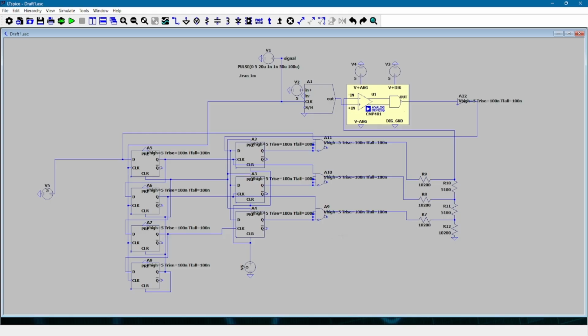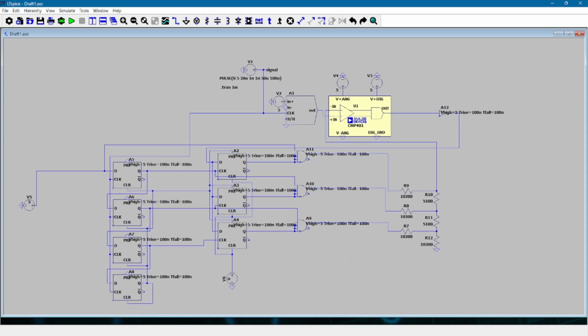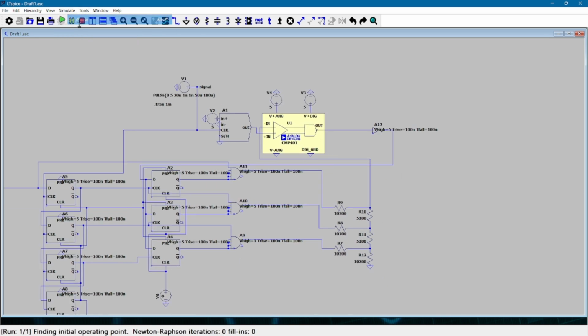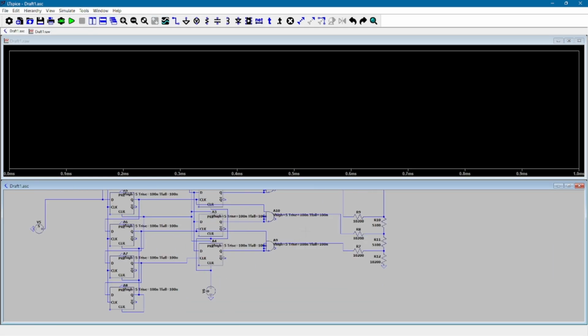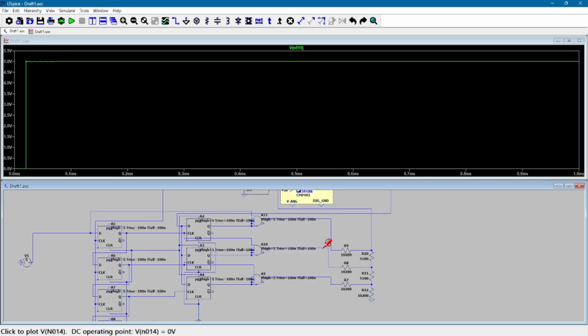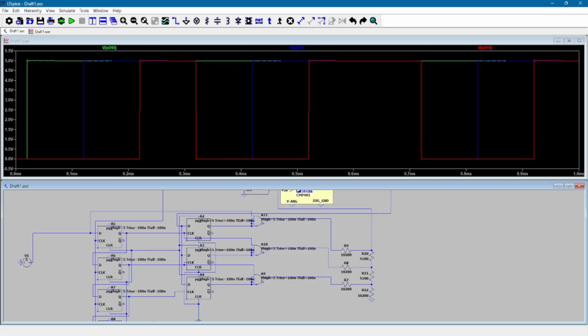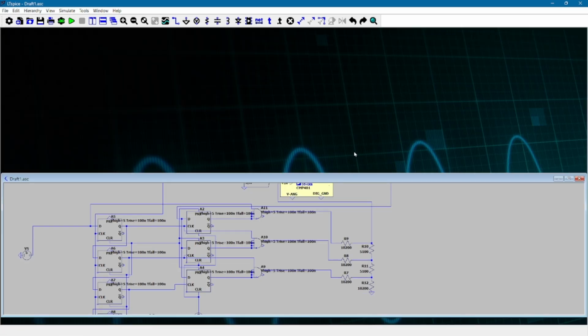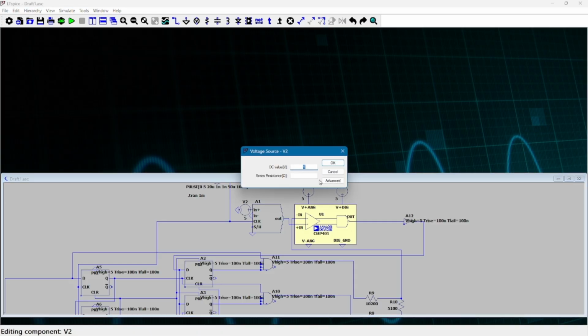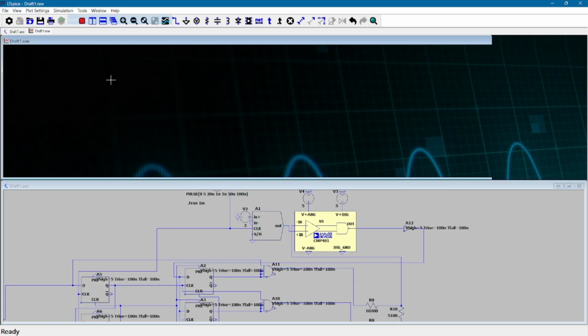So let's actually probe some inputs. We have 5 volts on right now. Let's simulate. It's 5 volts, referencing against 5 volts. If you had to take a guess, what will it give? High, high, high. These are just the waveforms from when it's testing. This isn't very interesting, so let's try an actually interesting voltage, like 3 volts. So, put in 3, simulate, run.